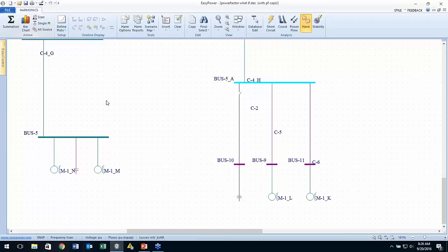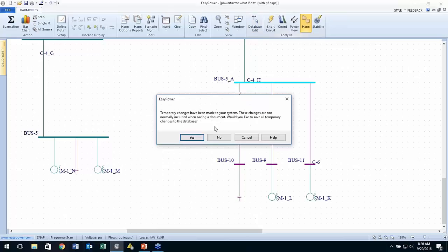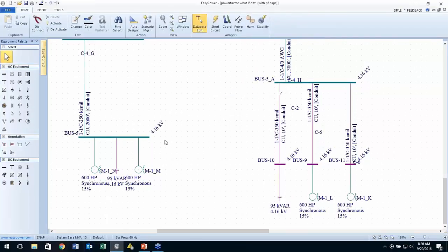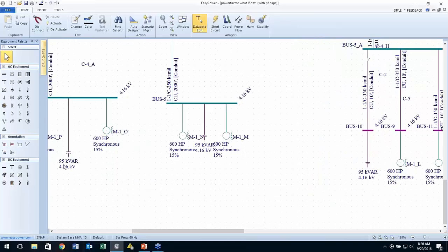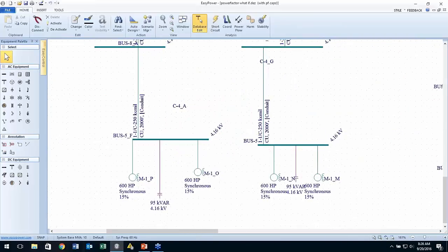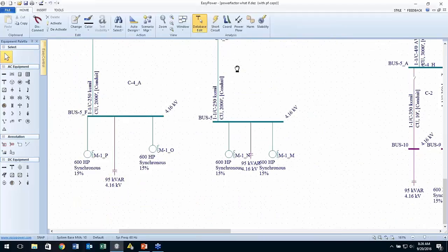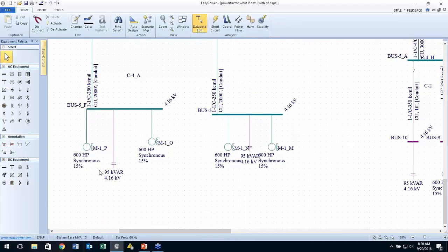Now, that's not necessarily harmful as long as I don't have frequencies at those resonance points. So now the next question becomes, what, if any, frequencies do I have at those points? Well, in the current database, because we're using synchronous motors, I have not entered any harmonics. So just for grins, I'm going to say, instead of a synchronous motor, what if we go ahead and put in a VFD? We can leave it at a synchronous rate and control these with VFDs.